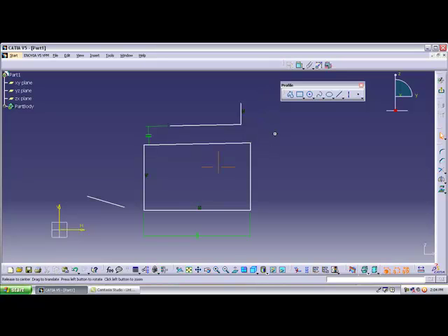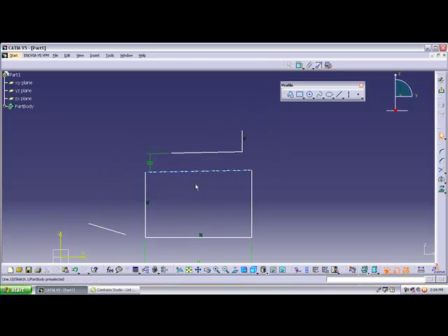And the next property is coincidence. What is the meaning of coincidence? Coincidence is nothing but making the two line paths the same. Suppose let us assume I am deleting the parallelism constraint. What path does it have? This line has a somewhat different path, and that line has a different path. If you extend this line, it has a different path. If you extend that line, it has a different path. So I want to make the two paths the same. For example, what can be made the same is the axis. We can align the two axes so they are the same.